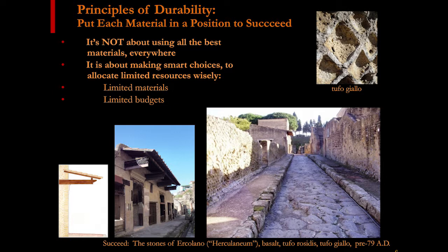And you think about this: you've got water kind of ponding between the curbs. You've got hoofed animals going over that. You've got wheels, these were metal-lined wheels in that day, going over that. So that's really taking a beating. It's sitting in the water, etc. So that's where they put the most durable stone. They had a stone of pretty good intermediate durability, tufa, which they used on the curbs here. So still a pretty harsh environment, but not as harsh, not submerged, not taking all the hoof and wheel impact. And then they had a stone that's just terrible, and it just totally falls apart,